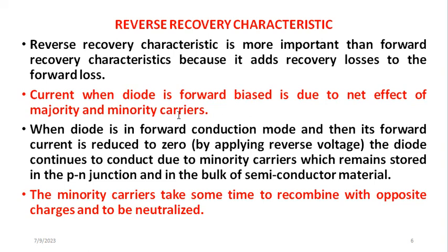But when the diode which was previously forward biased is now reverse biased, the current will start approaching 0 as I have shown on that diagram, and the diode will continue to conduct a very small amount of current, and I told you it is because of the existence of these minority charge carriers which exist at the PN junction, not in the actual body of the material, but the ones in the depletion region where the P and the N meet together.